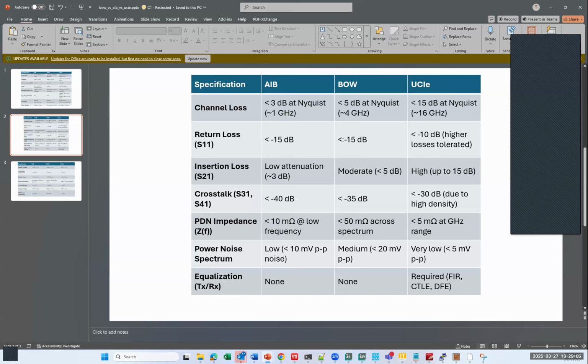Okay. So on our end, I'm working with the Siemens teams to get these masks pre-populated in all of our different wizards and forms, S-parameter post-processing, so that you have the S-parameters. If you know it's UCIe running 16, here's the frequency domain mask that you need to meet.